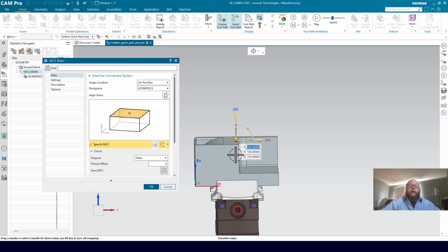So essentially, on the machine tool, we would likely probe, or indicate if you're a little bit old school yet, and then pick up that surface, touch off the top surface of the stock, and drop down that 5 millimeters of the extra stock we had. I'll go ahead and specify that we're also going to use fixture 1, and we'll see. I'm not sure what machine tool we're going to use yet. I'll have to think about that as we're working. We have a few different machines that we could put this particular job on.